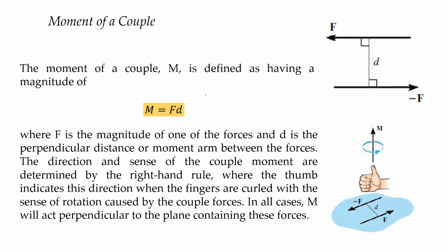So it means that, let us say, if you have your systems here, you have another force there, going down. Let us have this as F sub 1, F sub 2, and we take the moment about here. So we have moment is equal to F sub 1 times its perpendicular distance from, let us say, this is O, from O plus, or I'm not following the correct sense here, F sub 2 times its perpendicular distance from O, and then we add this couple here.